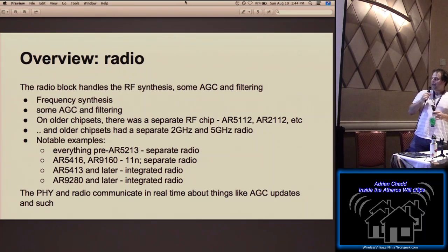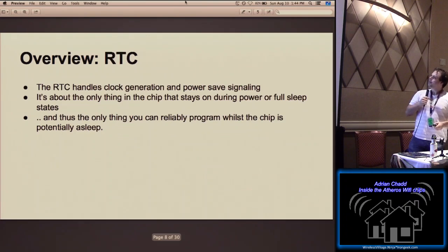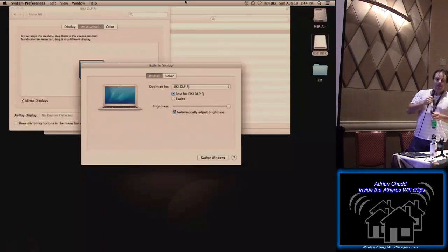The only thing that the PHY and the radio communicate is AGC updates. You can program the radio directly, but you only do that to configure the synth. You don't actually touch it after that. And the RTC handles all the stuff dealing with clock generation and...